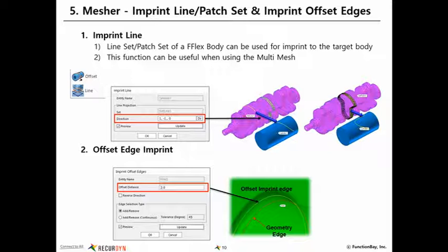There's a certain line where you want your elements or nodes to line up, or a certain patch set that you want to line up with a second piece of geometry. To really demonstrate this, we'll go into an example so that you can see how that works. But it's very useful for lining up two pieces of geometry and having a little bit more control over how the mesh is going to happen when you're just using this auto mesh.